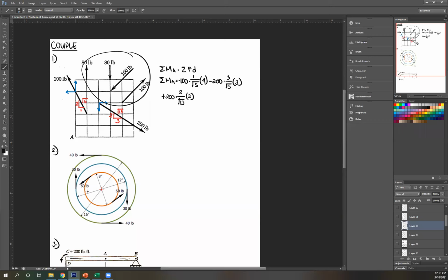Now we have these forces right here. And if you've noticed, let's start with AP, they are equal in magnitude but opposite in direction. So we have an example of a couple. So what we do with a couple, if we're taking moment, you're just gonna take the force multiplied by the distance between them, and sign convention applies. So rotate your couple. This is upward, this is downward, upward, downward, upward, downward. That is clockwise. So that's positive. So positive, this force is 80. Then the distance between them is 2 sides or 2 blocks.